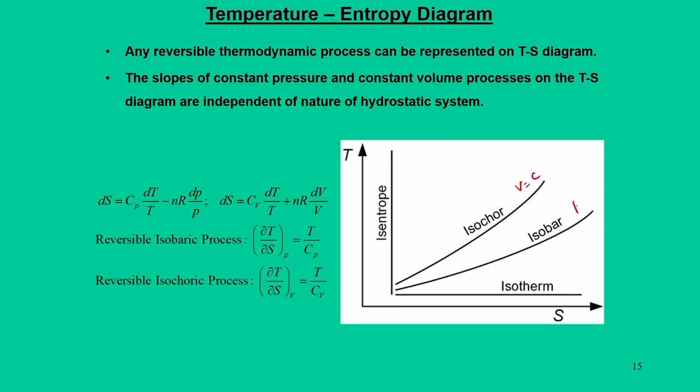There is the isobaric process, where pressure remains constant. We can also talk about an adiabatic process, where Q is equal to 0, which is not necessarily isentropic, but is adiabatic. We can also talk about the polytropic process.